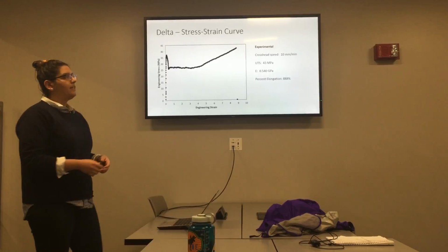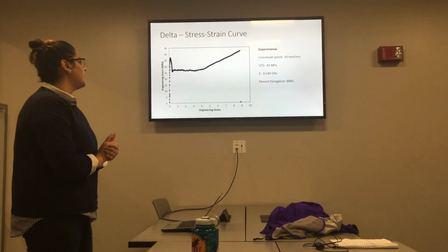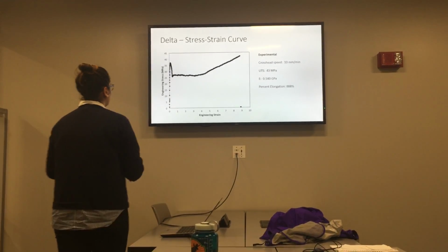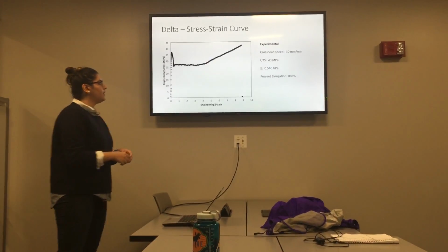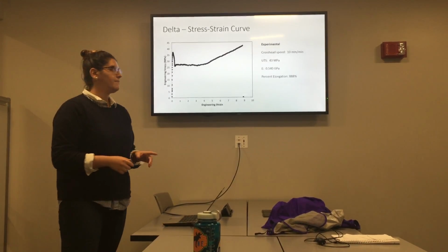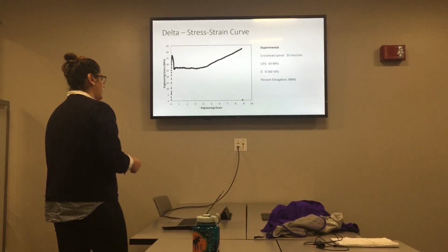I just want to remind you that even with metals, looking at an elastic modulus from a stress strain curve isn't the best idea. So I really don't want you to focus on the elastic modulus. Definitely just focus on the ultimate tensile strength.